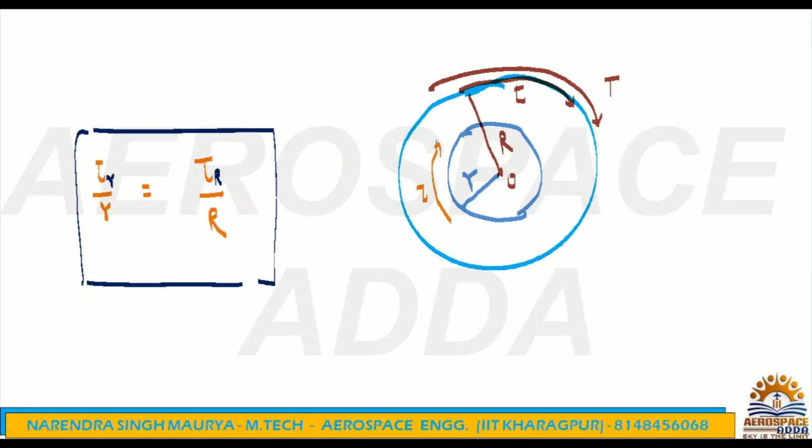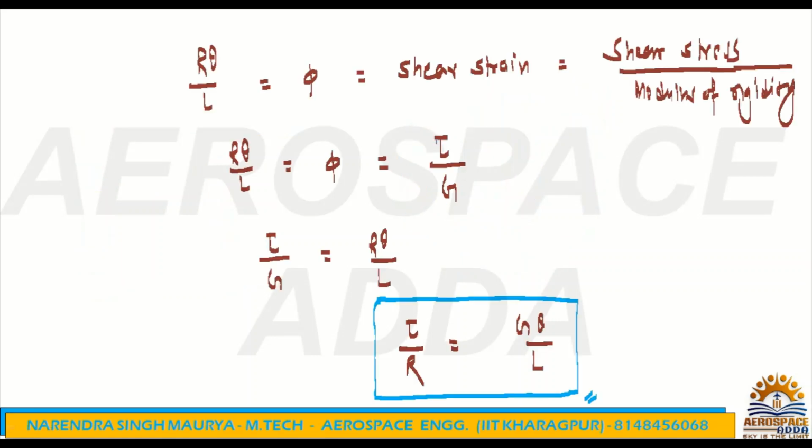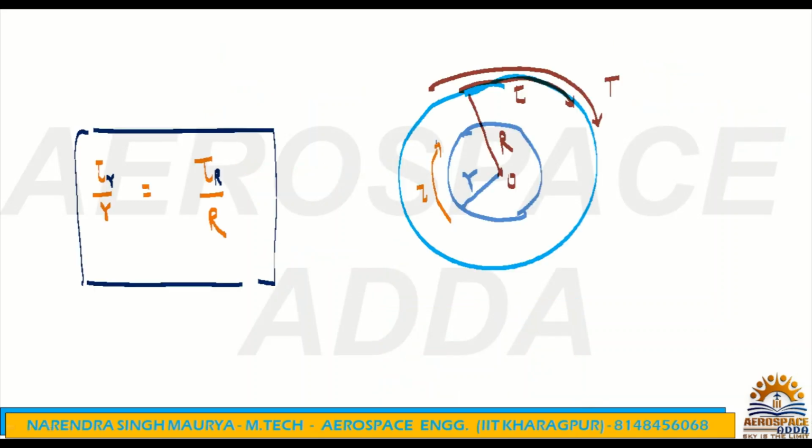Now coming to this, because the problem is not solved yet, we also have to calculate the torque. With respect to the torque also we have to derive the formula, because till now we have only defined shear stress. We got that relation: shear stress, r radial distance, G modulus of rigidity, theta the twisting angle, and L the length of the shaft. But still we have not derived the twisting moment formula. So we are now interested in the twisting moment formula, so next we can go for it.